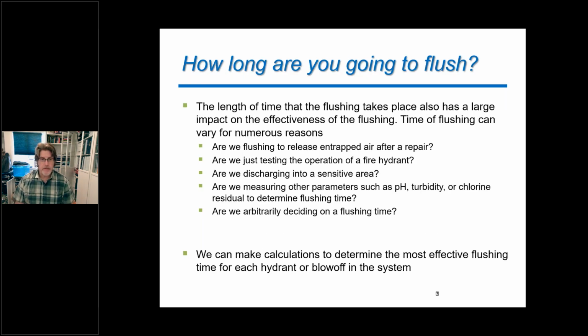Now, this is always the big one: how long are you going to flush? By once again looking back to our question of why we are there, well, if all we're doing is trying to release entrapped air after a repair, then we're just going to flush until we don't hear air coming out anymore, and that should be good enough. Are we just testing the operation of a fire hydrant? That can be very, very quick.